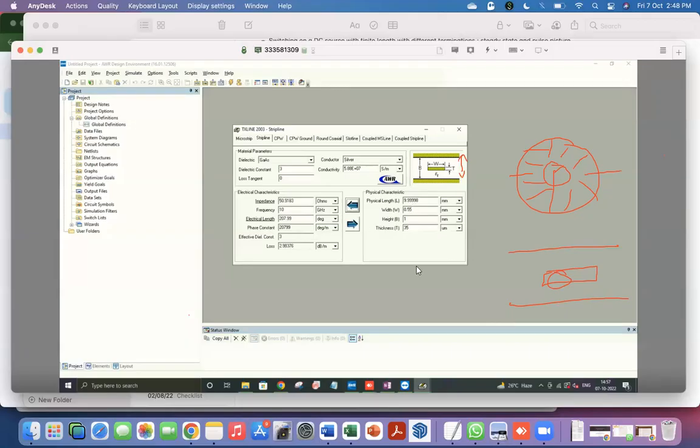So I almost need something like 0.55 millimeters for a total height of about 1 millimeter. So you can see the aspect ratio is actually quite small in this case. The plates are quite close to each other in order to get 50 ohms. Part of this is of course related to the relatively low dielectric constant we have used here, of 3. If this was higher, then automatically the widths will become less.